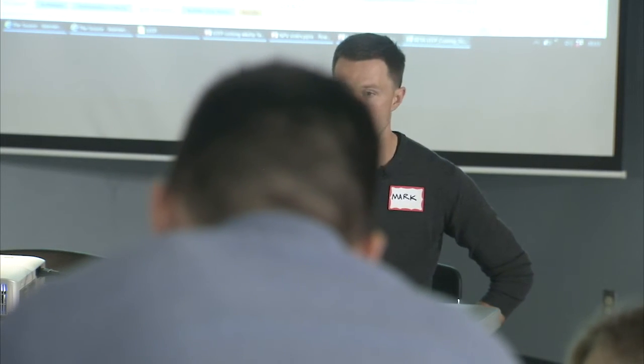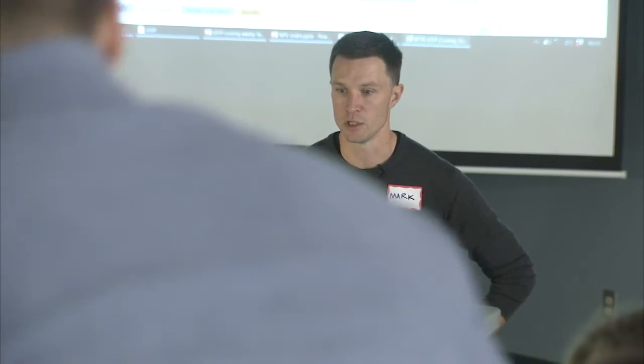We're going to change our net zero approach from net zero ready to net zero. So your top table should look like what's up on the screen right now. And now we're going to go back to our ECM selection tab, and we're going to click Run Optimization, the big green button at the top, so that it'll generate a solution now based on PV.